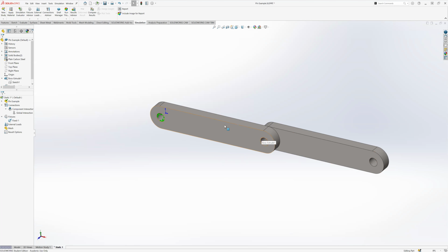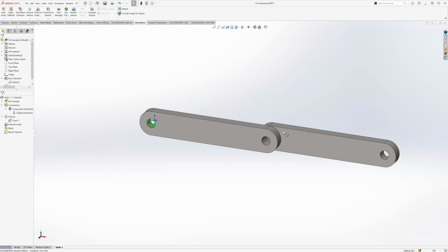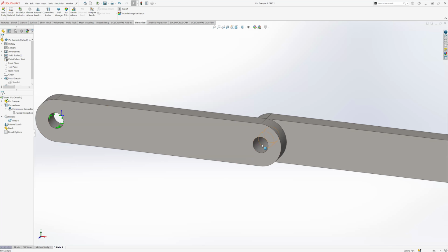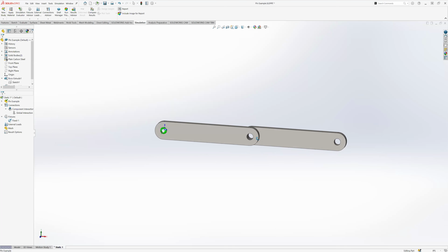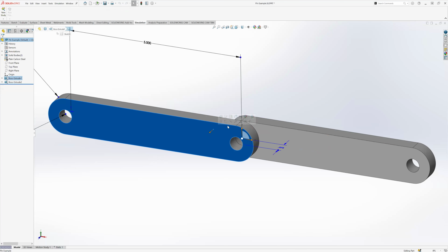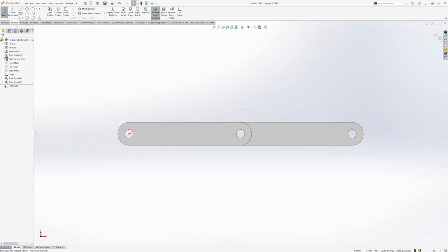So then I'm going to try to have these go together. Typically what you could do here is just do a pin. I could actually just do a body going through here, and I might do that just to show before I get into the pin constraint. That might be a good way of doing it. I'm going to go back to the model real quick and do a new sketch on this face here, just to show how you would do it if you didn't use connections.